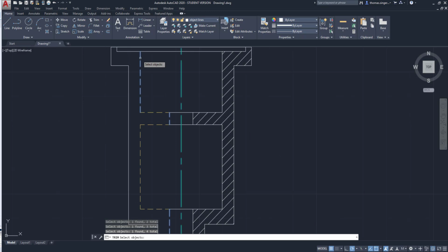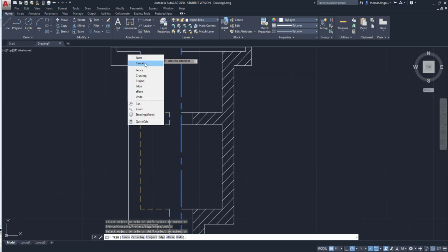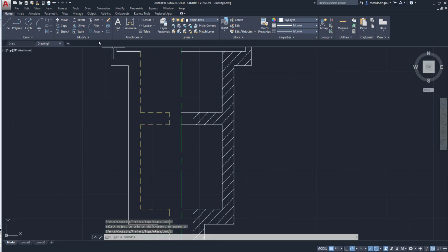Okay, so to trim these up, we're going to go ahead and select the center line and the hidden lines, right mouse click, and we'll trim out the sections that are going to need to become hidden here. So those 3 sections are going to be hidden, and that section is going to need to be hidden. This line I can actually choose to be a hidden line. So we'll draw these sections in just as standard individual lines now as opposed to part of the longer lines.